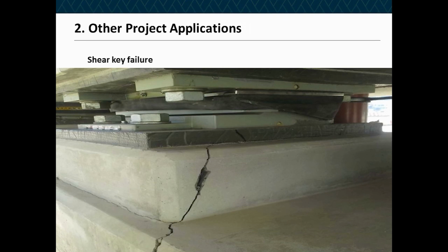But essentially this had happened because of the people involved in the design. One person had done the track structure interaction to find out what the forces were on the substructure, and one had done the track structure interaction to find out what the stresses were within the rail. Now, once they'd done the rail analysis, they determined that they needed to move the movement joint in the rail. So they moved the movement joint to a position that was immediately over a pier that was fixed in both directions for the opposing spans.